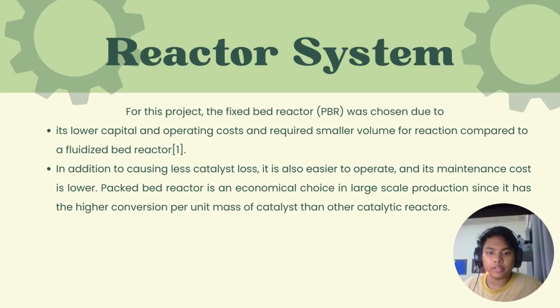So for the reactor system for this project, we choose the fixed bed reactor (PBR), and the reason we choose it is that it has a lower capital and operation cost and requires a small volume for reaction compared to a fluidized bed reactor. In addition, there is less catalyst loss, and it is also easier to operate and has a low maintenance cost.